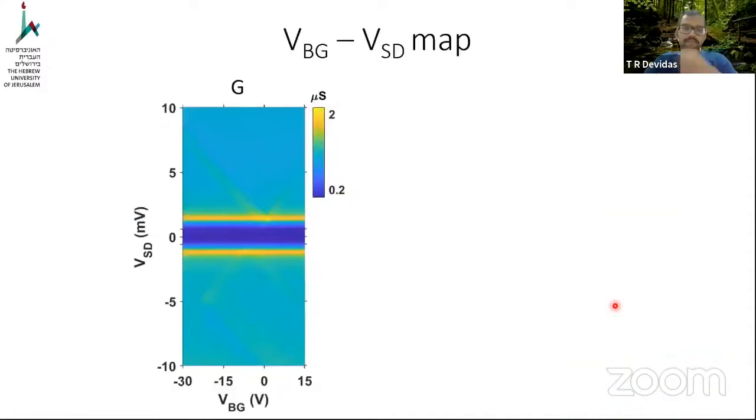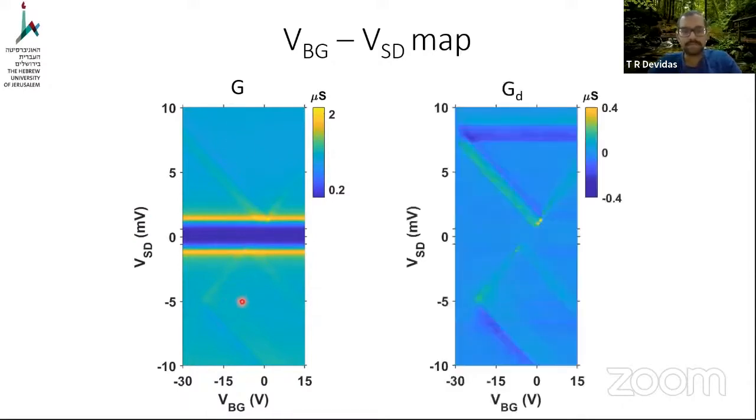As we proceed with measuring the spectrum over a wide range of gate voltages, we get a conductance map, V_PG versus V_SD. As we see, we have a dominant dot-assisted tunneling feature on a background of a constant tunneling spectrum. We then subtract an averaged background over different gate scans to just extract the dot-assisted tunneling current.